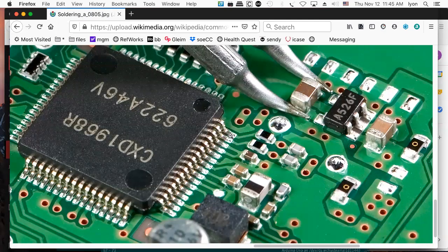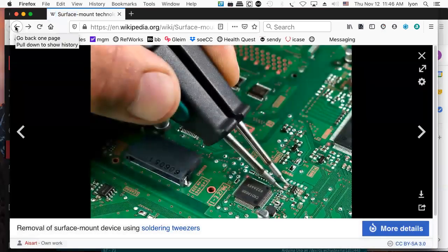But if you wanted to do it upright in production, you get a stainless steel stencil along with the printed circuit board. Then you squeegee on your solder paste just enough to go through the thickness of the stencil. And then you do the pick and place operation on all of the surface mount stuff at once. And then you chuck it in the oven, give it a bake, and then the reflow occurs, and you've got yourself a completed board.